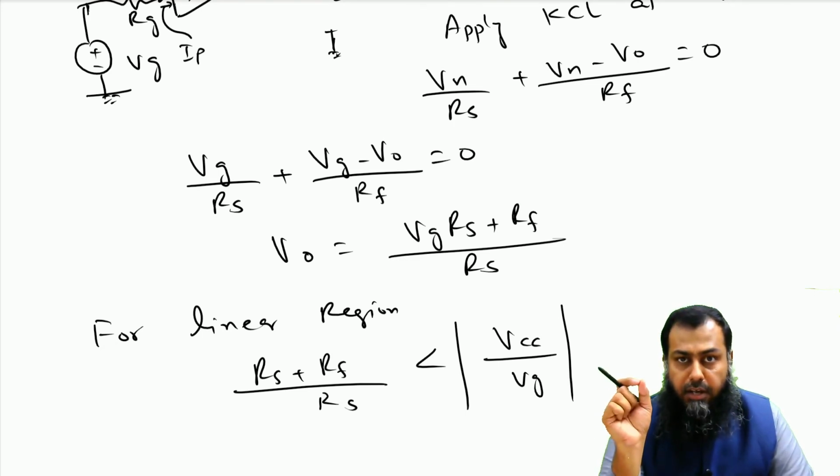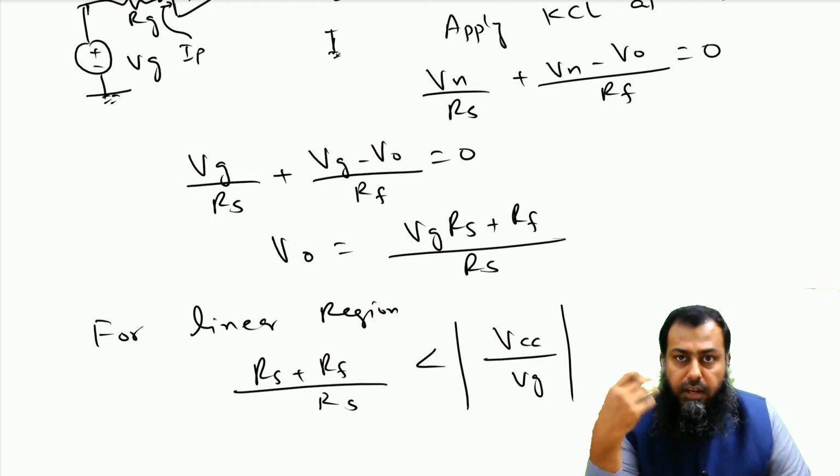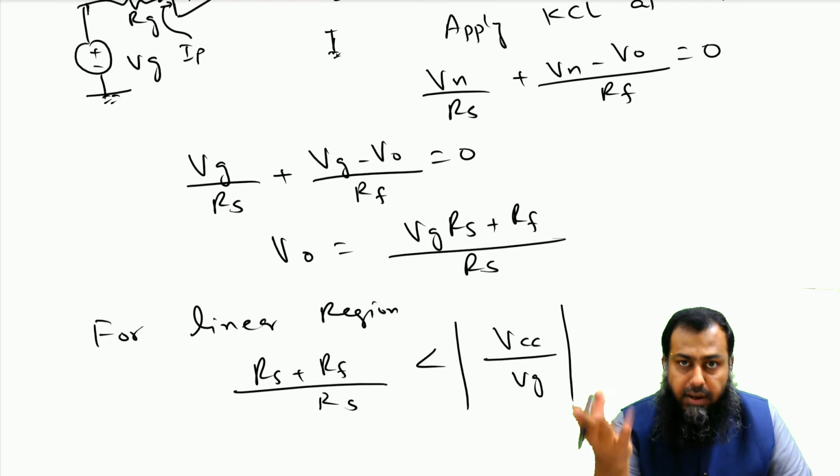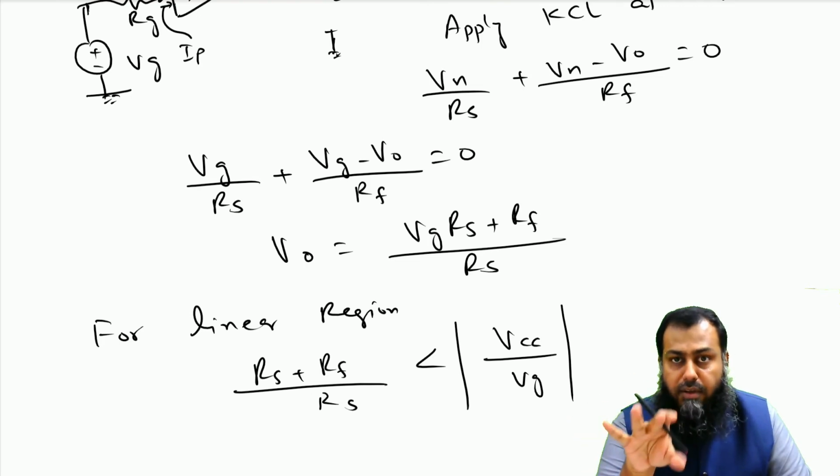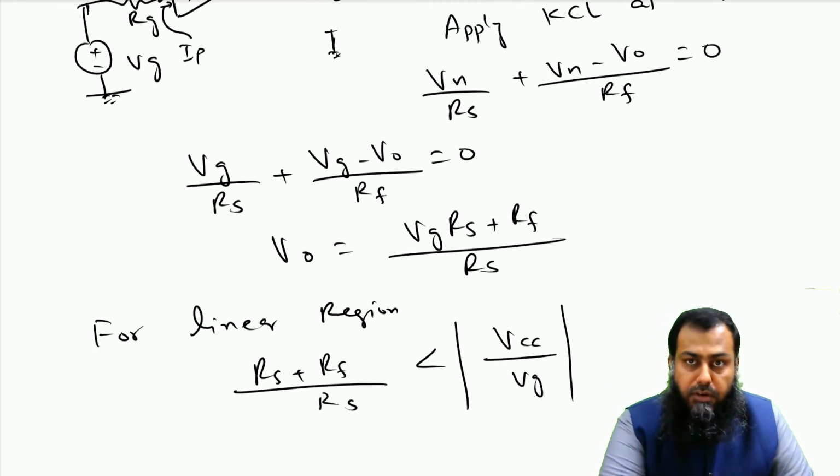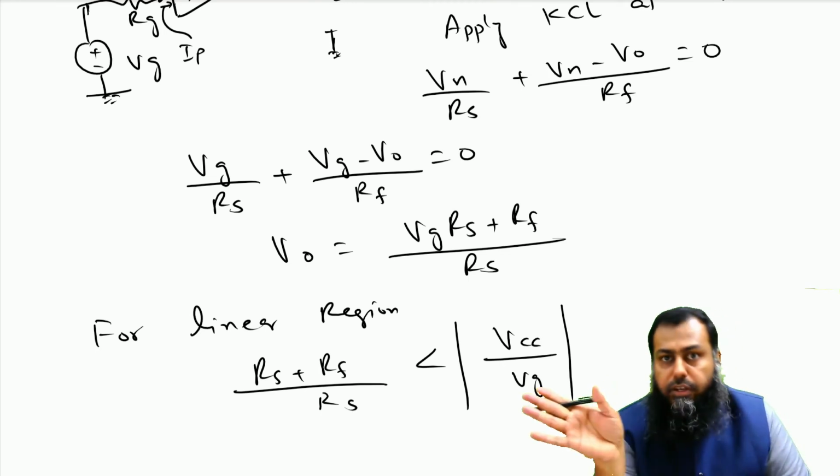So that helps a lot while applying Kirchhoff's current law on the input side. The output current I naught is not equal to 0. It does have some finite value, but you cannot actually identify that value unless you have the required information on the output side. So the key of almost all the circuits of operational amplifier lies in starting from the input side and then going on to the output side.